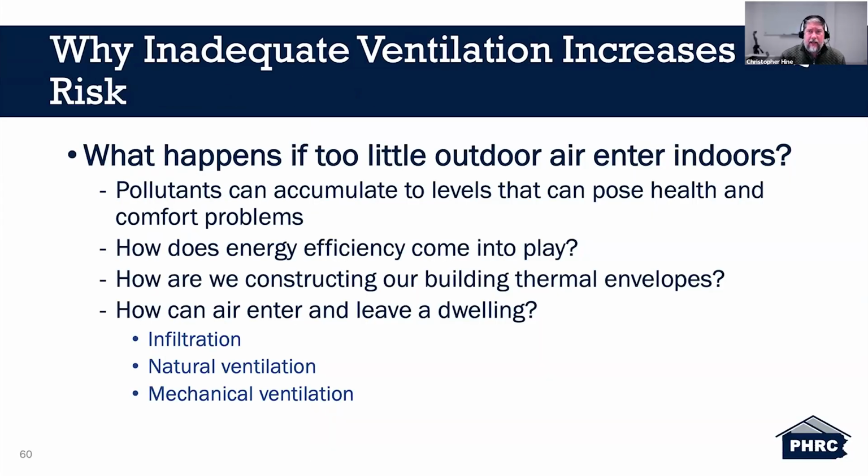So why does inadequate ventilation increase your indoor air quality risks? What happens if too little outdoor air enters the indoors? You have an increased accumulation of pollutants. How does energy efficiency come into play? Well, you look at our energy efficiency codes now, and we keep tightening up that building thermal envelope. Again, not to repeat it, but that's the most cost-effective way to increase energy efficiency, to tighten up that envelope. But adversely, you have to increase your ventilation, right?